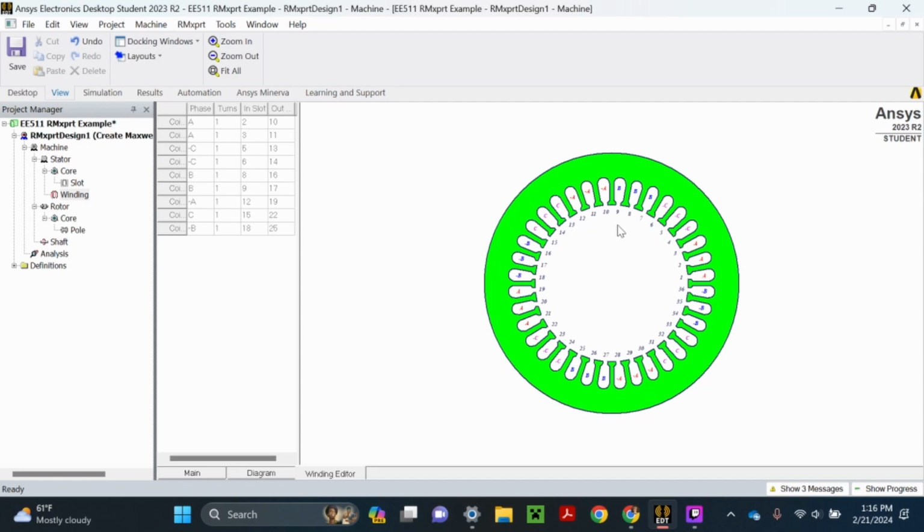Okay, go ahead. Yeah, basically what I was trying to say is these slots are facing out and these slots are facing in. So then if you can imagine the 3-phase, if you have this phase A, when it's at the peak value, there'll basically be field lines like this. And that would attract the 4 poles from the motor.